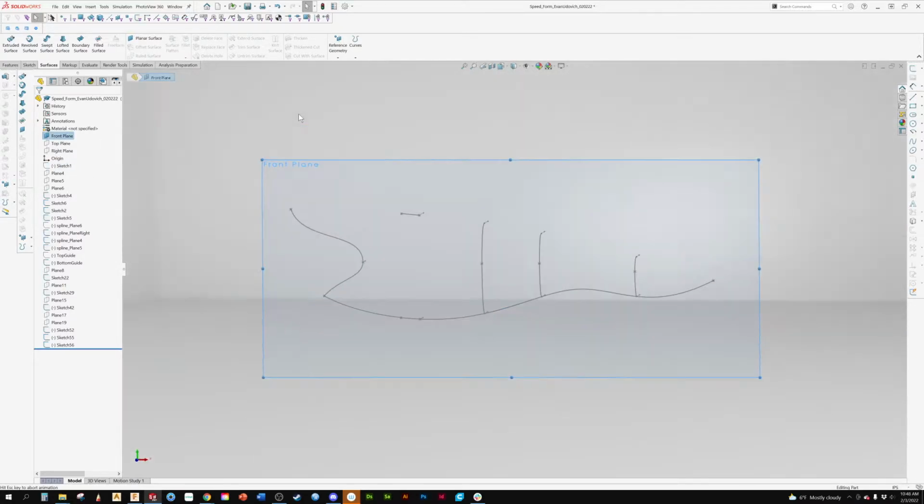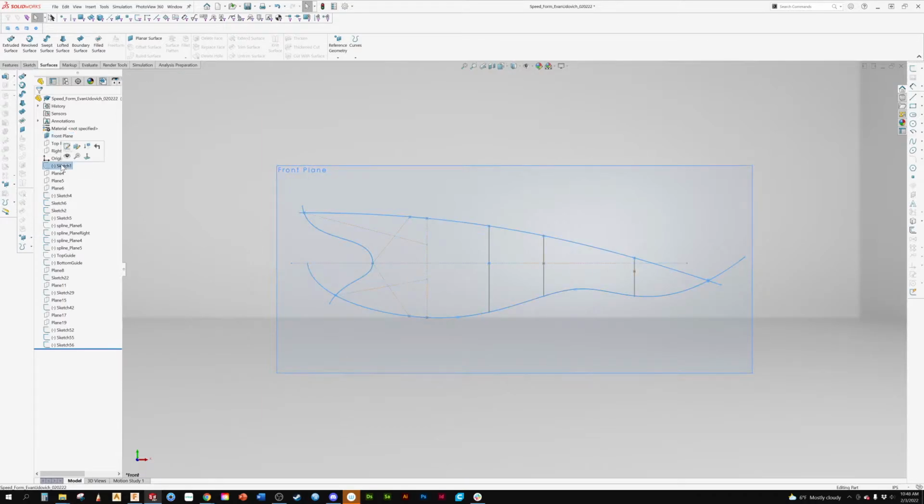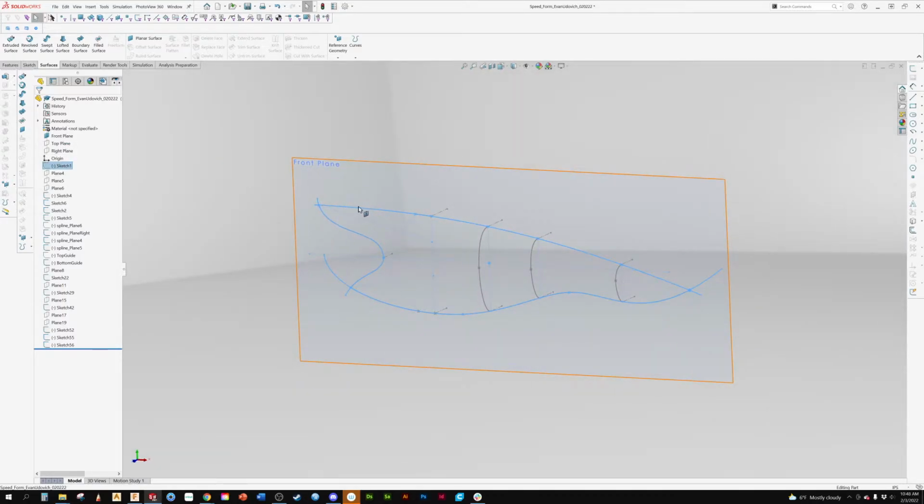And one of the things is, this initial exercise that was provided was about taking this and having your splines, or figuring out how to make your splines match your concept sketch. It doesn't necessarily mean that you should be using this entire sketch, which has all your curves on it, as an individual sketch to build things off of.